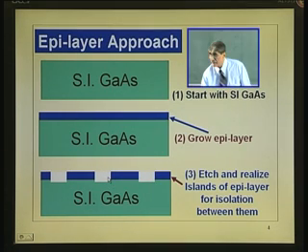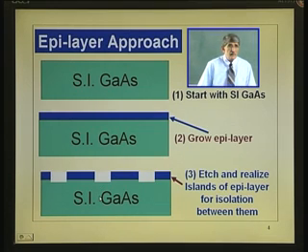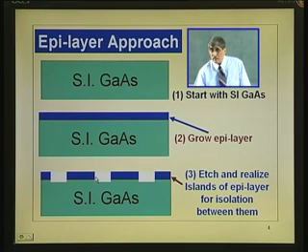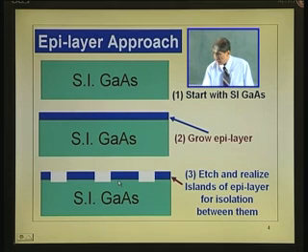separated by this gap, and this portion which is connecting them is semi insulating. It is not insulator, but semi insulating. Therefore, the isolation between these two layers is very good. Now, you can make the device. In each island you can make one device, put them together so that they are isolated from each other. This is the first method, which is very popular.